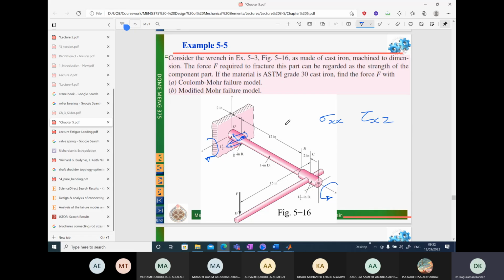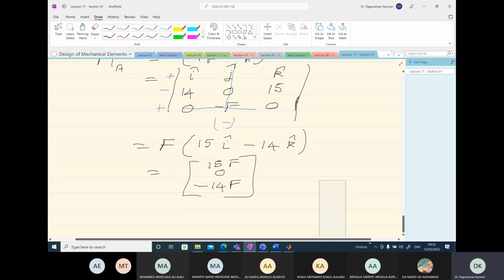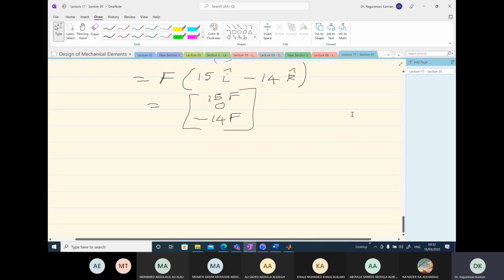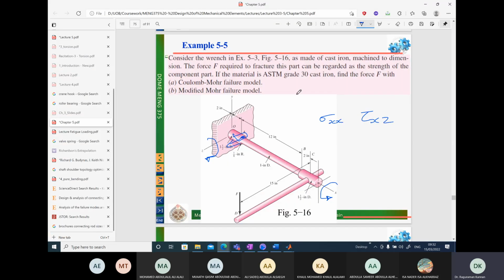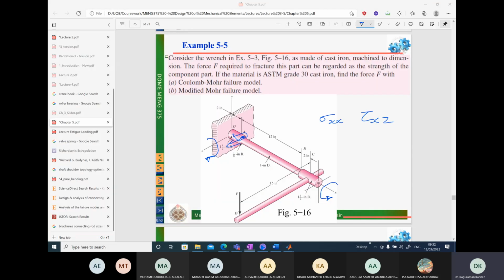Once we draw that, we can see in the xz plane what is the direction of the stress, and then we can figure out what the components are. So let's first draw the stress element here on the xz plane. When I look from the top view, I'm going to see my x-axis here, the stress element over here, and the z-axis going down like that.